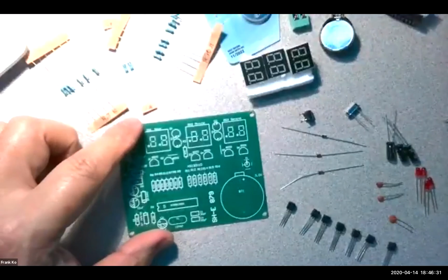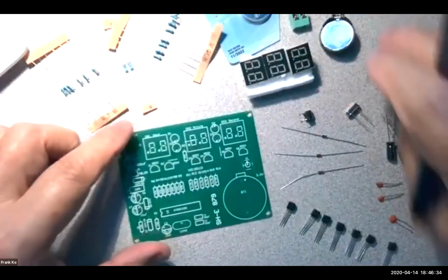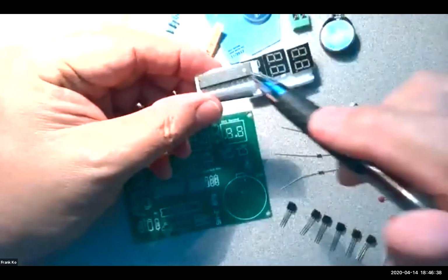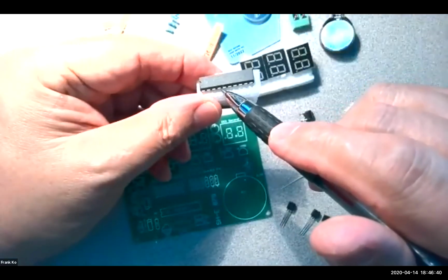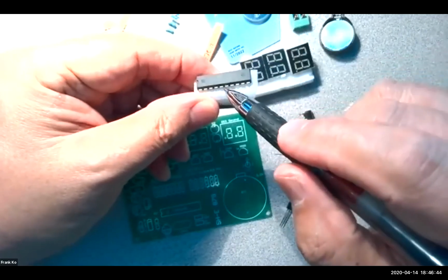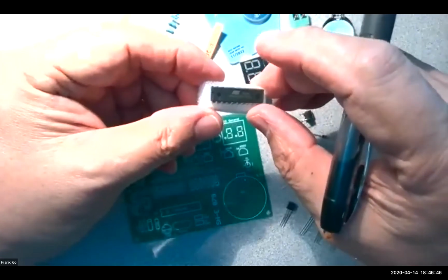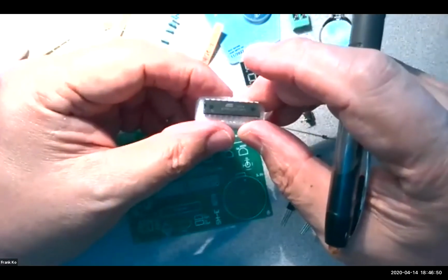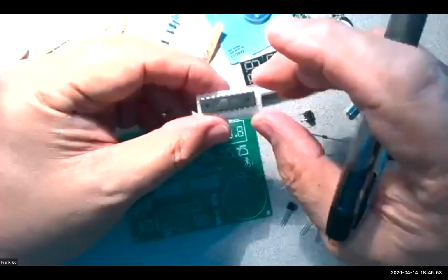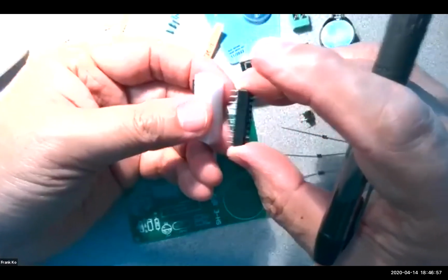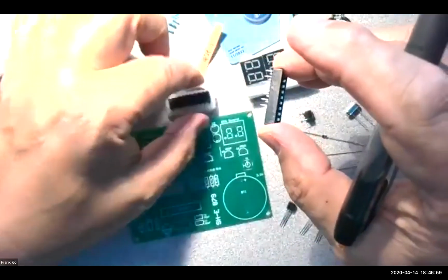That's discussed. Now, as before, when you're playing with a chip, this one has many pins, 20 pins. When you're playing with a multi-pin chip, it is put into an anti-static block. Before you touch it, make sure that you yourself have not been moving around a lot, generating static electricity on your clothes.